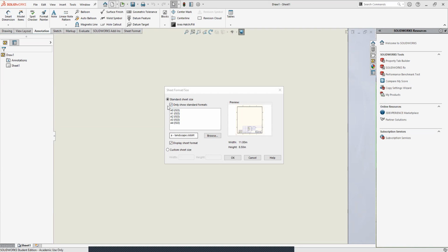Awesome. So quick question. The first thing you have to do is select a format and size. Do you have only these 5 listed in your box, or do you have more listed? I have more. That's good. So that probably means you have this unchecked. The drawing format that I have always used is ANSI. I've never used ISO. Maybe if you work for some company or go to a certain school, they might want you to use ISO, but I have never used it.